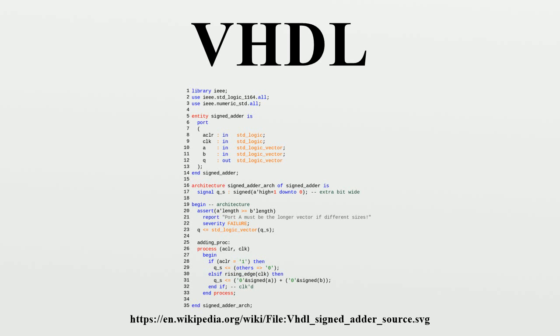Advantages. The key advantage of VHDL, when used for systems design, is that it allows the behavior of the required system to be described and verified before synthesis tools translate the design into real hardware. Another benefit is that VHDL allows the description of a concurrent system. VHDL is a data flow language, unlike procedural computing languages such as BASIC, C, and assembly code, which all run sequentially, one instruction at a time.